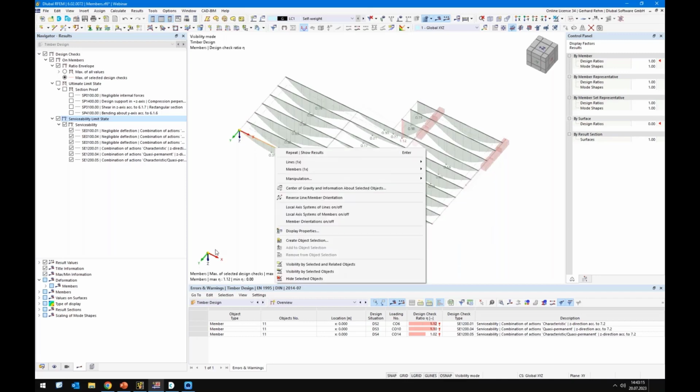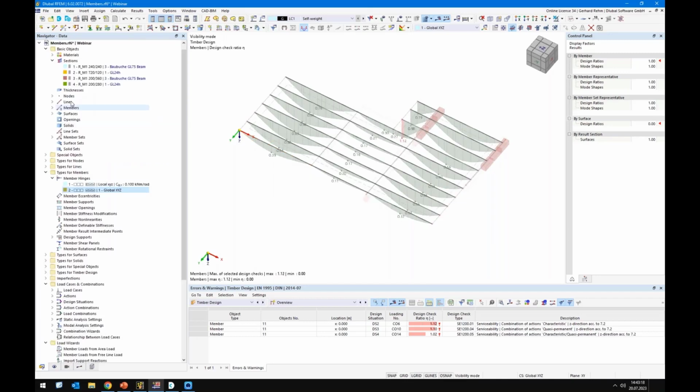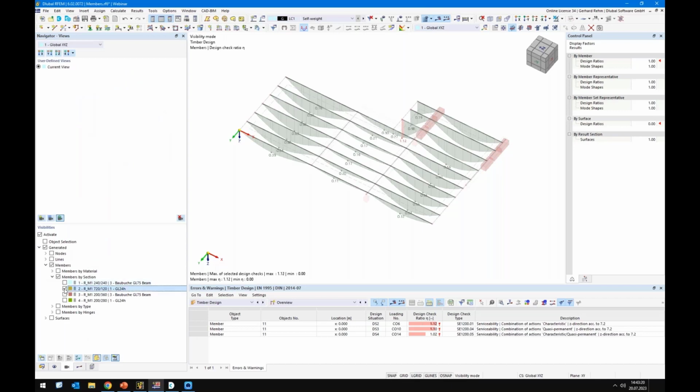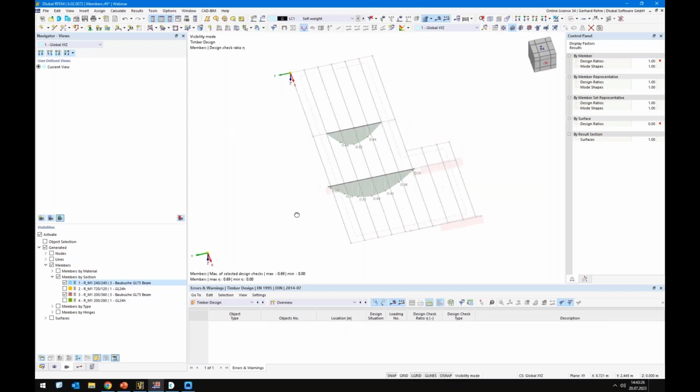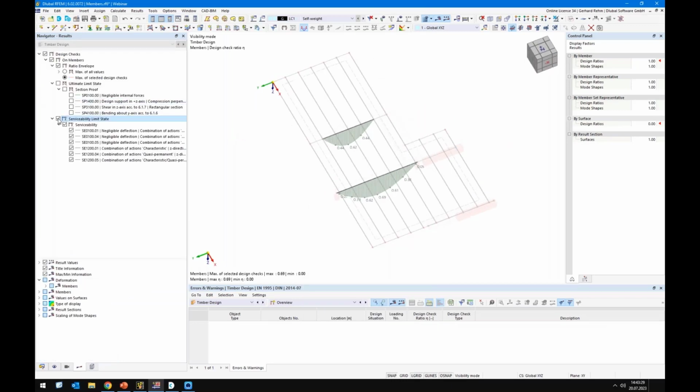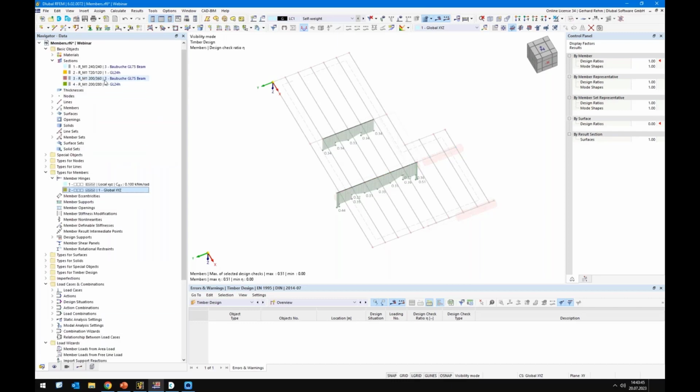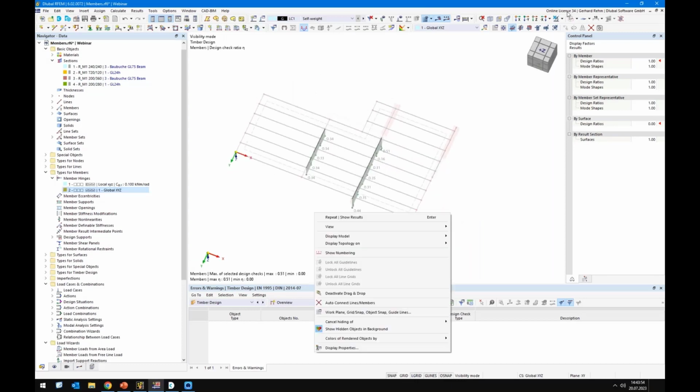Okay, and let's check also our Baubuche beams, sorry. It was section number 1 and 3. So we have a ratio for SLS of 69 and 62, and ULS, yeah, extremely small. So maybe worth talking about changing it to 320 millimeters. So now we have 200 by 360. Then yeah, we can change it to 320, but that's okay for now.